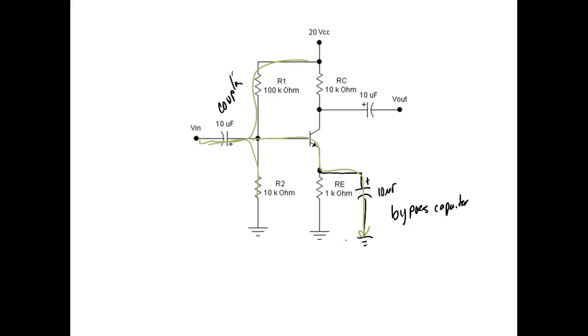Now what are you saying? It looks like it's a short circuit, but it's not. What we do is we have a junction right here, and this junction has a resistance. It's got an R value. And we looked at that when we did our characteristic curve: we came over here and we noticed that thing was at a slant. Well, what causes the slant? It's the R of the actual junction itself, right?